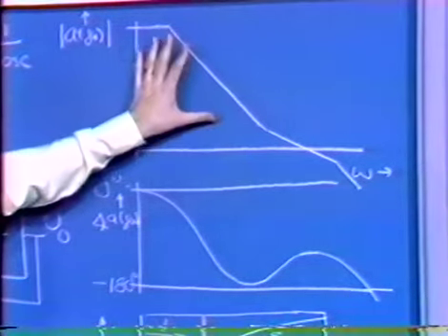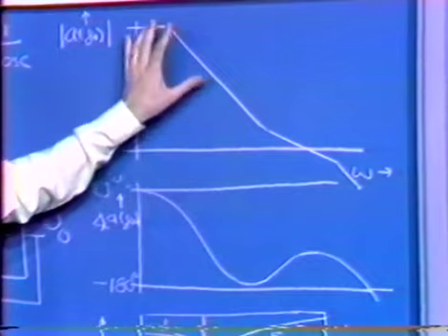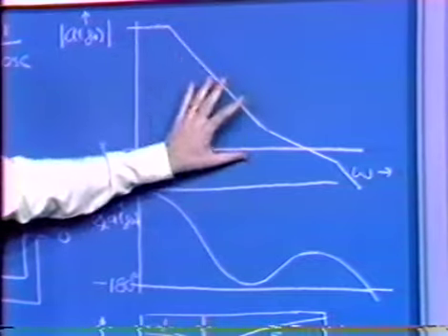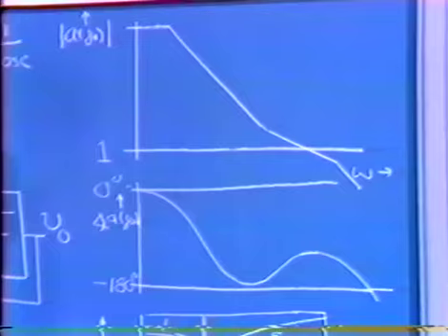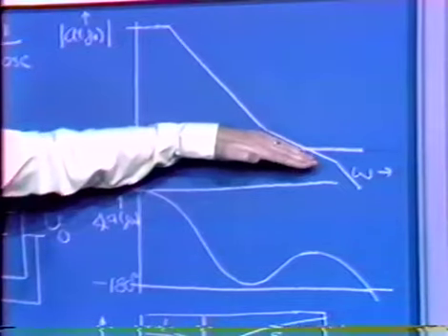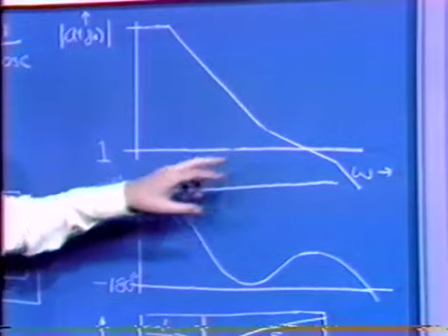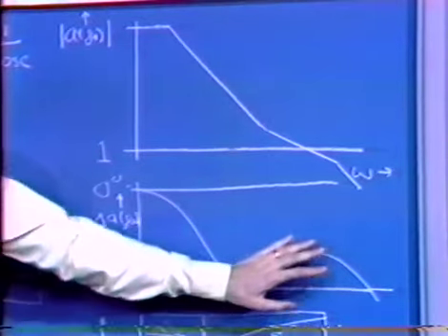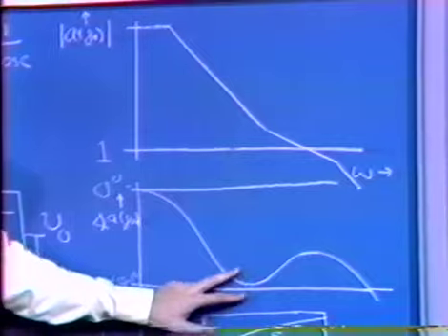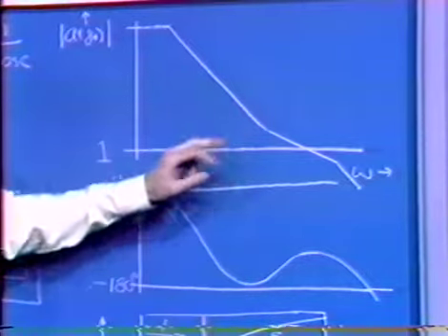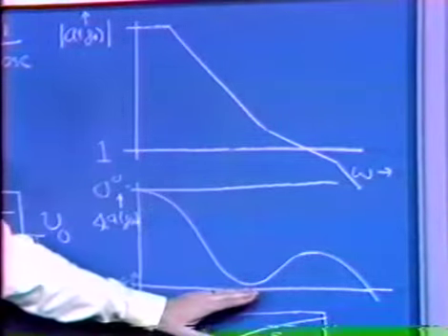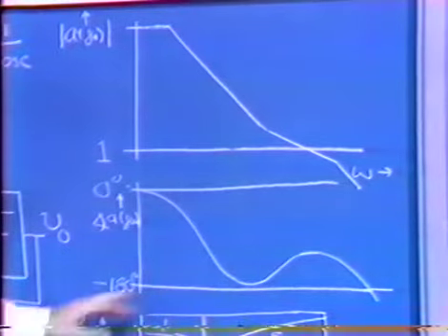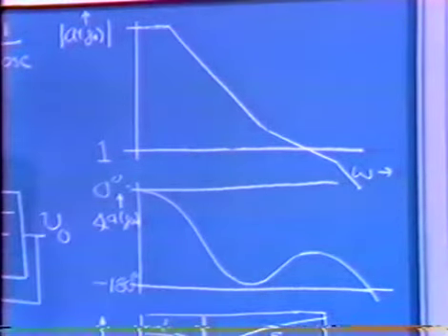In the case of our operational amplifier, that 1 over s squared region might last for a factor of 100 in frequency or something like that. And then we had a 0 so that we went through unity gain, or unity loop transmission magnitude, with a slope of 1 over s in that example. But again, we'd anticipate that the phase curve might look something like this. Particularly if there was a 100-to-1 ratio between these frequencies, we would get down quite close to minus 180 degrees over some range of frequencies.